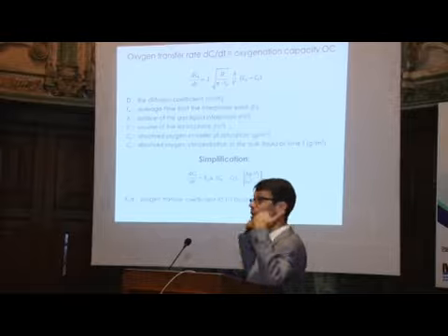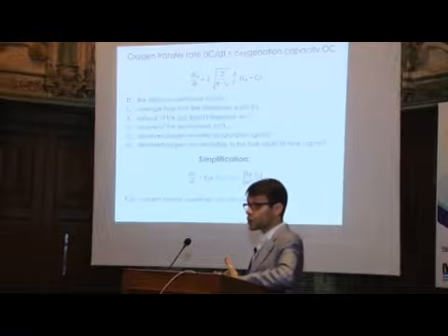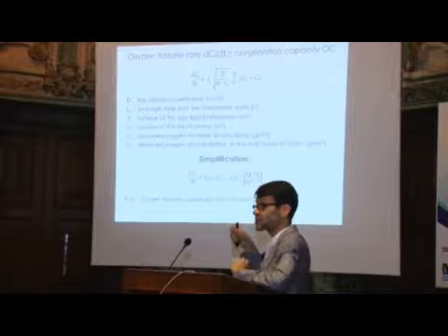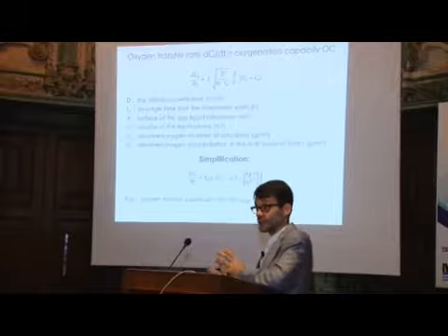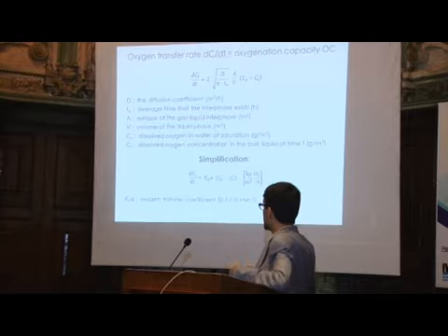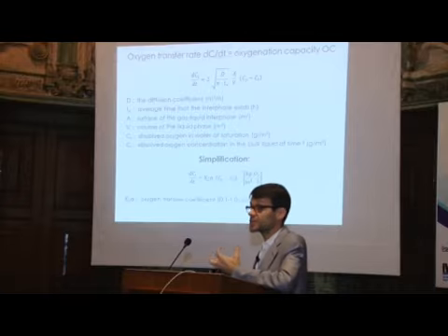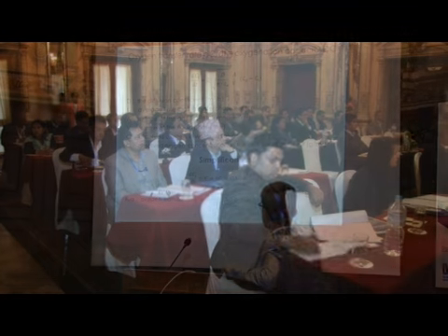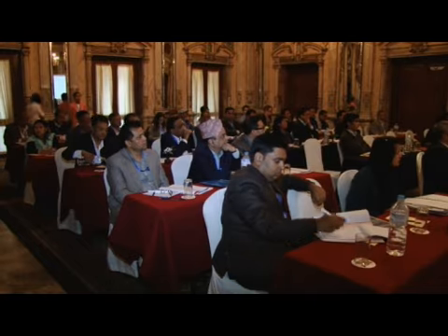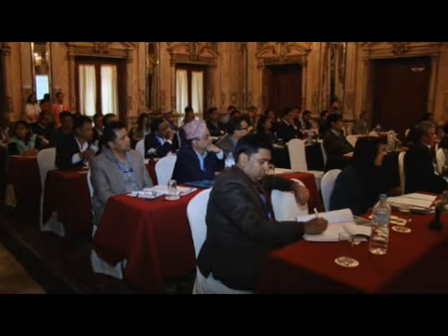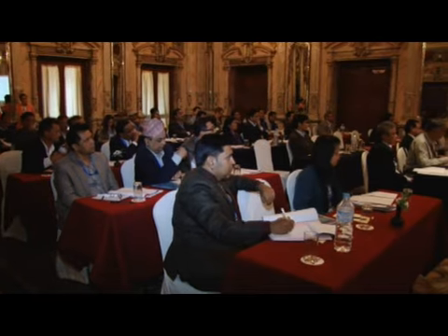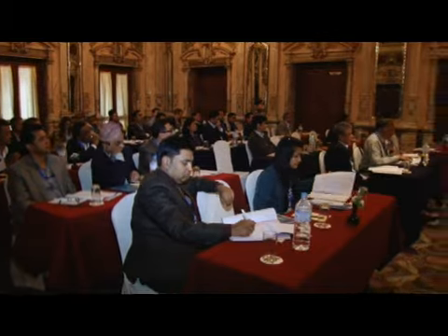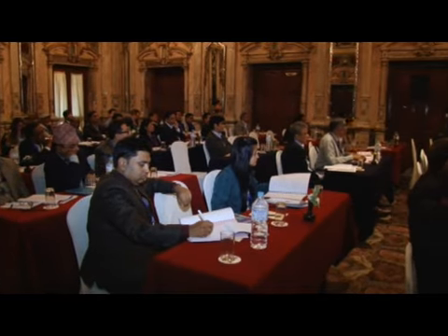Clearly, you need to be above certain oxygen levels also to get good rates in terms of the Monod kinetics, in terms of substrate removal, and to prevent, depending on the case, anoxic zones or anaerobic zones, if that would not be good for your process at that stage. And actually, this brings me to the end of this very fundamental, quick introduction on organic carbon, biological organic carbon removal.